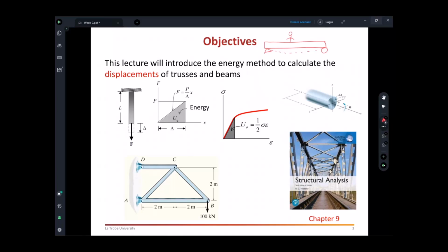You can't say from this quantity that because it deflects too much, it has failed. There are no rules in structural design and analysis saying that by looking at the deflection, you can say that the beam has failed or not. Yes, bending moment and shear force can be used to check whether the beam is safe or not safe. But for deflections, this is not the case.